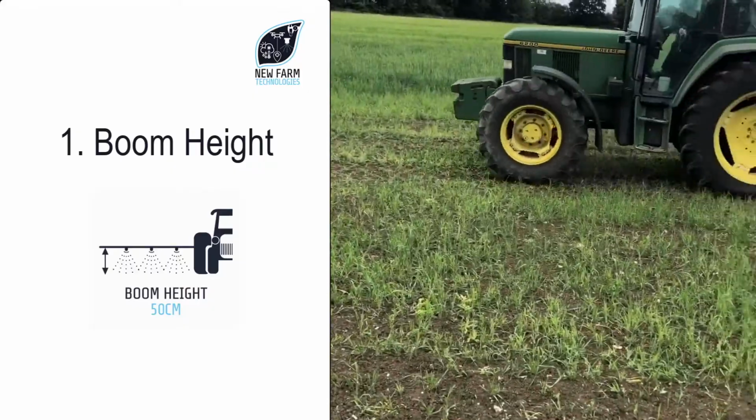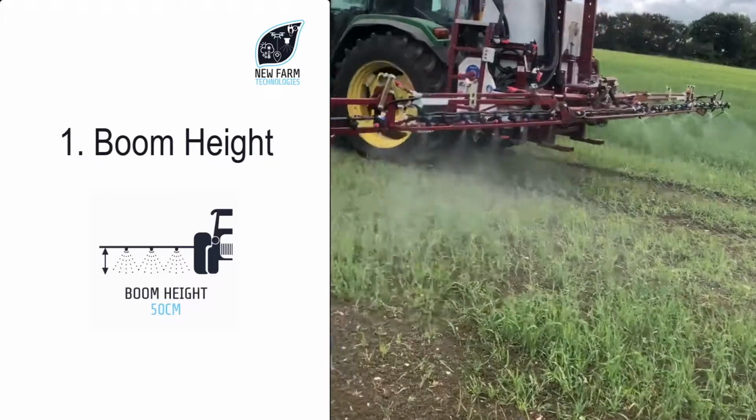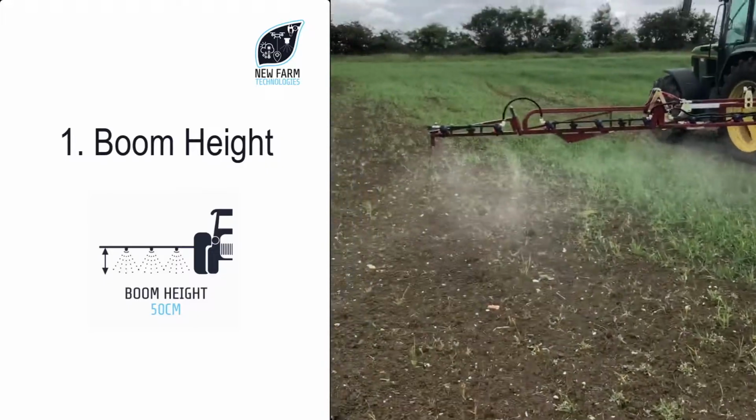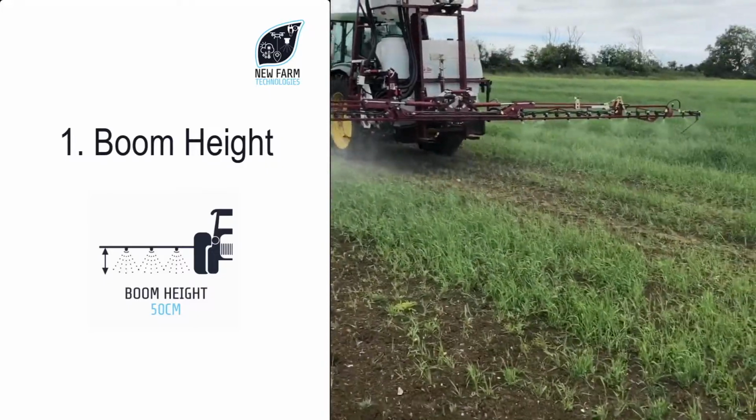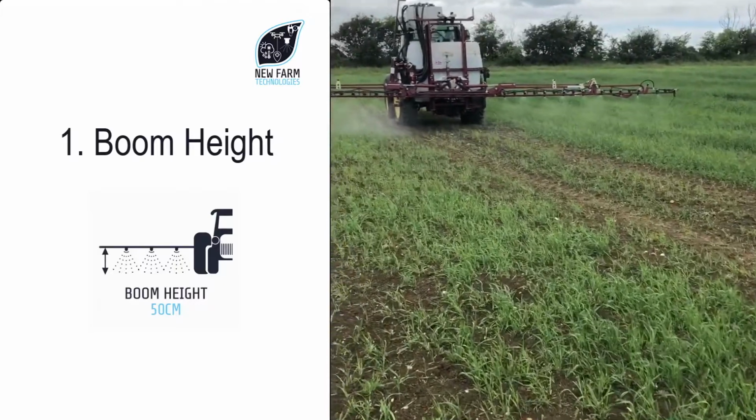You can see here Tim has got the boom at 50 centimetres, and he is spraying at about 8 kilometres an hour. Very little drift, sensible forward speed, and on the 3D90s a lovely pattern with very little drift.